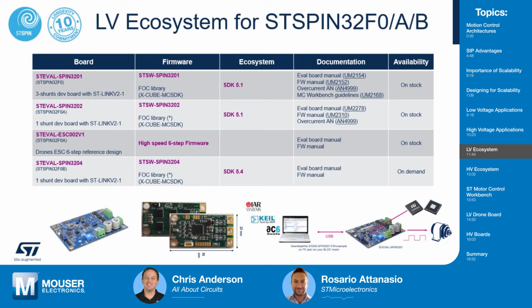The boards can be divided into general purpose boards and application specific boards. So if I look at the STEVAL-STSPIN3201, this is a general purpose demo board that implements a 3-shunt topology and is supported by a field-oriented control library. We have already talked about the firmware packages. So we have both sensored and sensorless FOC, or sensored and sensorless 6-step modulation.